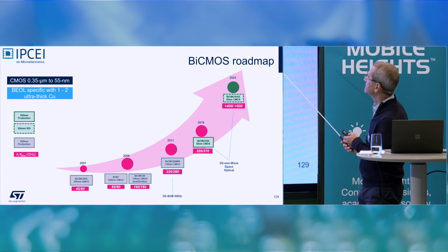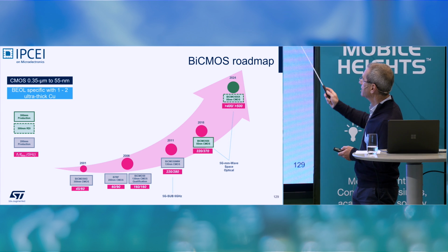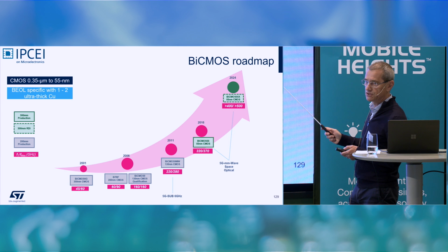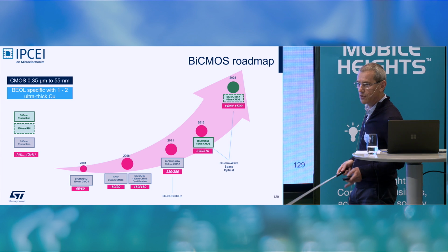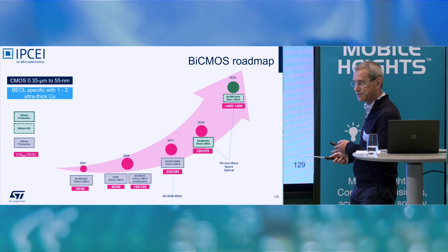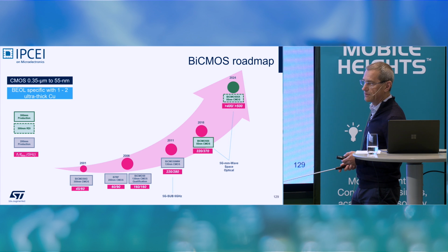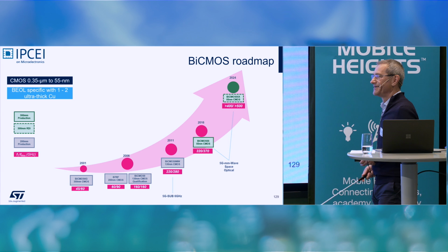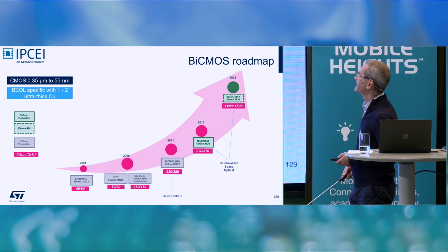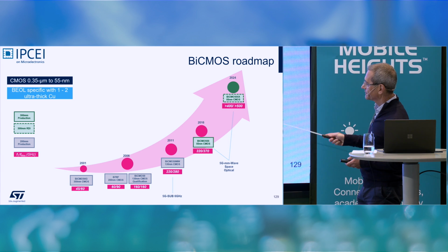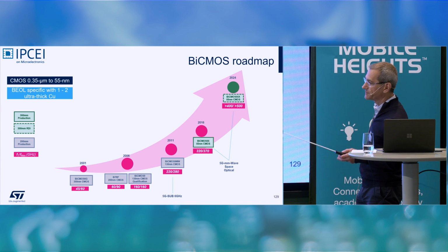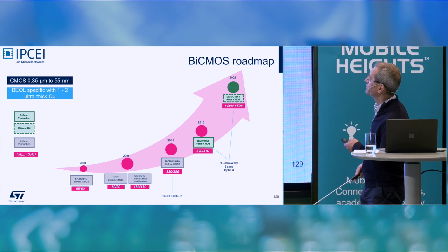Even we think this kind of SiGe device can go up to 700 gigahertz later on, and even higher, but not so high as InP in the future, I would say. But it's not so expensive a technology, as expensive as the previous RF-SOI technology shown before. So it's a very interesting technology.